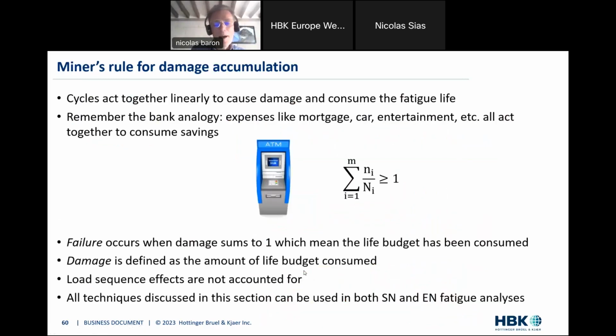Miner's rule. Let's get back to this bank account analogy we had before. And Miner's rule is just this in the end. Think of fatigue failure just as you withdrawing money from a cash withdrawal machine. So you will have some number of cycles repeated over time, and your component is able to withstand a given number of these cycles at a given amplitude. So each time you withdraw money, it's the same, from an engineering perspective, as imposing a loading force on your component for a given number of cycles.